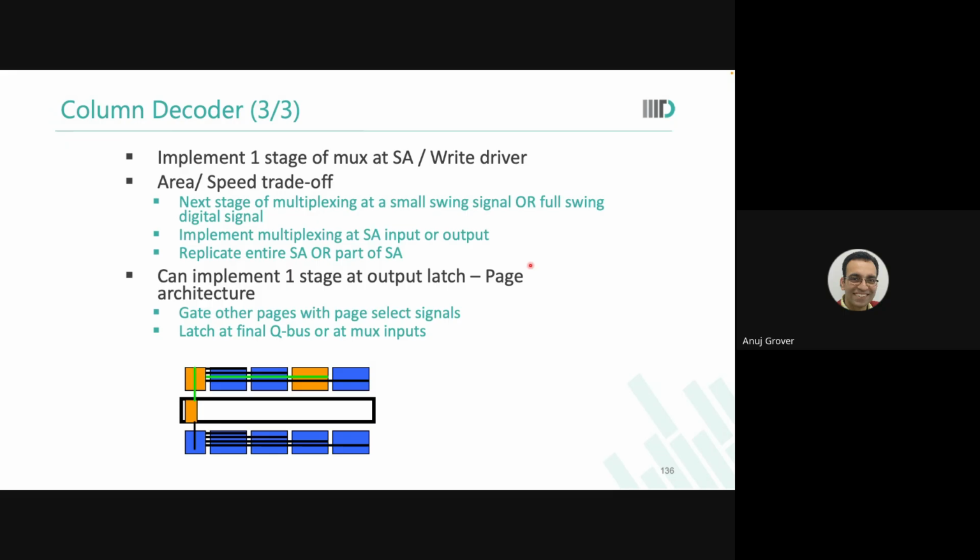So we talked about these write assist schemes, and we said that if you have MUX greater than 1, there will be a challenge. Yaad hai? If you have to use write assist schemes, you can't go for MUX greater than 1 inside the memory array. But you still need to change the aspect ratio.